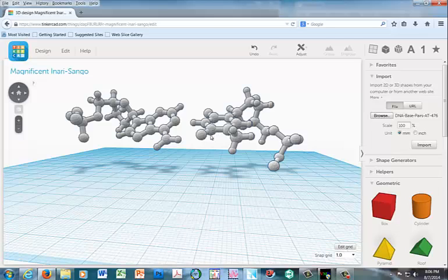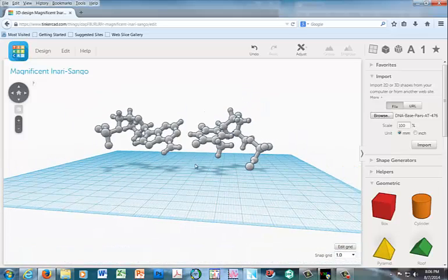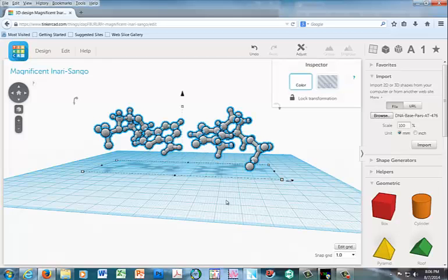So when the 3D printer tries to deal with this, it prints things on one another, right? So it'll actually print over this area twice. If you work in Tinkercad, when you're all done, the file that it's going to generate for you, the final STL, will actually just be the skin of what you're finished with. And that's one of the key benefits to working in Tinkercad.